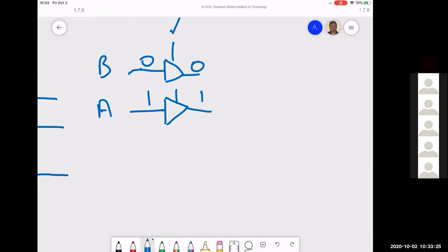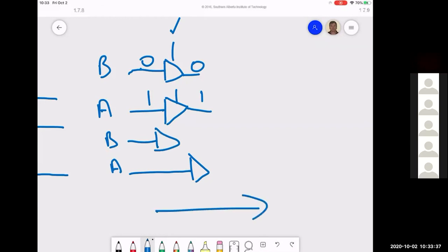So if A arrives a little bit later than B, it doesn't matter. You don't release until I tell you, at exactly the same time. Therefore B and A will change at approximately the same time. This is what buffering does for us on a control system on the input.